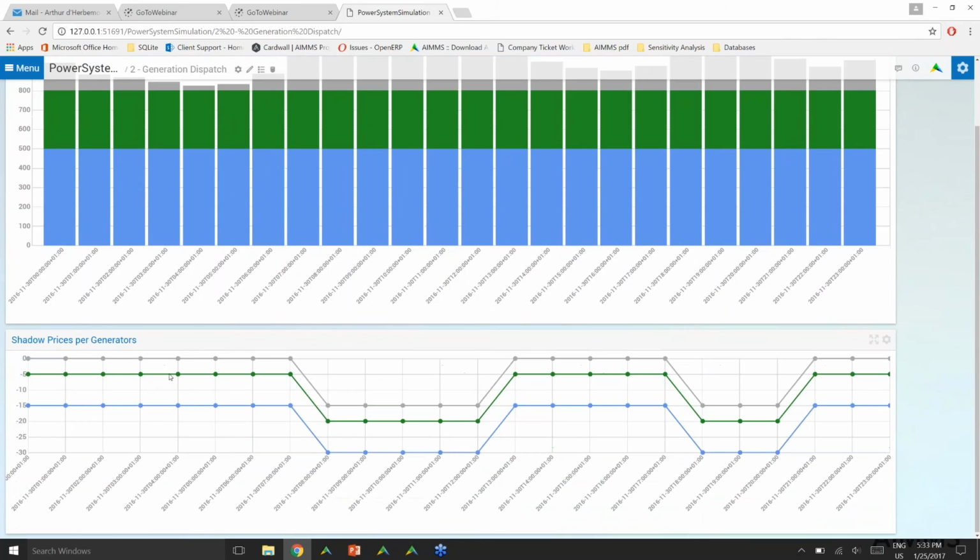And we can extract the shadow price from this capacity constraint thanks to AIMMS. So for example, here, the hydropower plant, the shadow price of the capacity constraint, because the hydropower plant is binding, this capacity is binding because it is at its maximal power. So the shadow price is $15 per megawatt, okay, so which is the right-hand side.